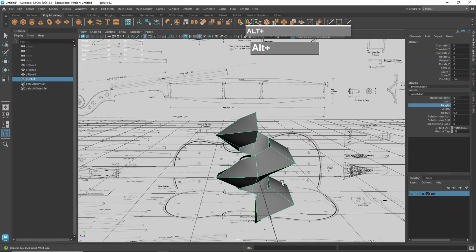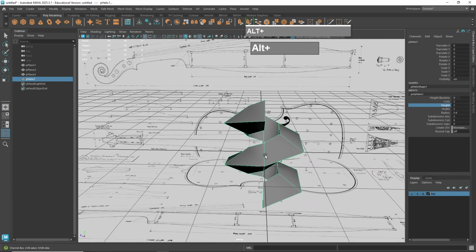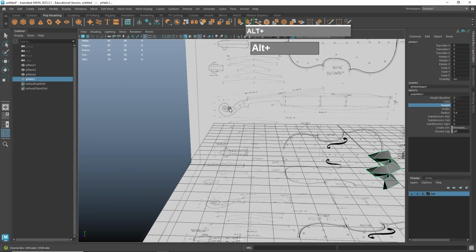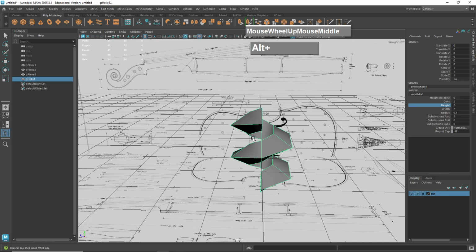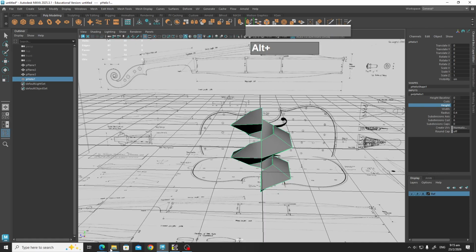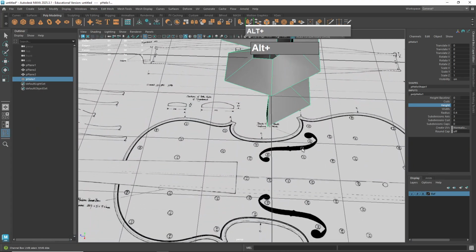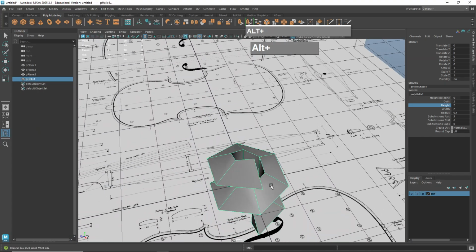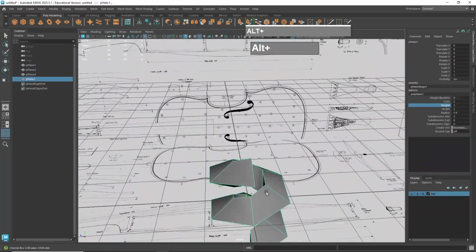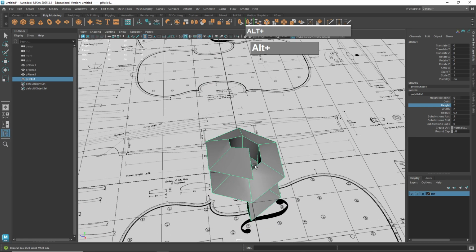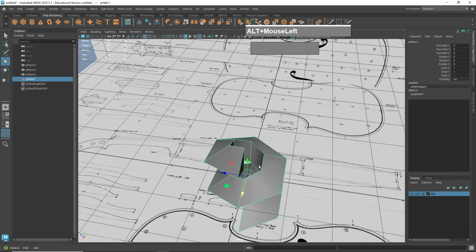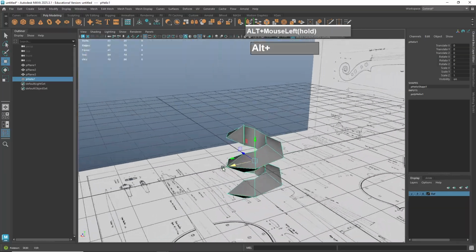Okay, but we also need another object to help us. You will notice that the spiral shape is deformed. That means if you look at the side of the spiral, it starts out small, then it gradually expands outwards. So we need to use a deformer to actually change the shape. Then later, we can manually move the shape to form it. So I'm deliberately using a low number of faces here, because later I know that I can subdivide this. If I press number 3, I can subdivide this to get the smooth curve that I want.